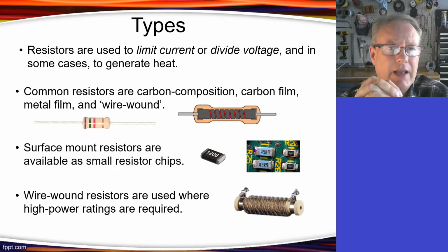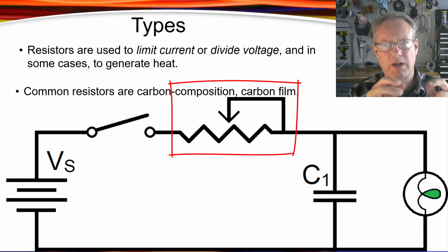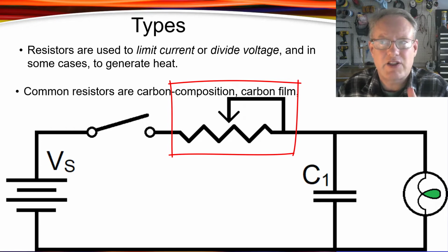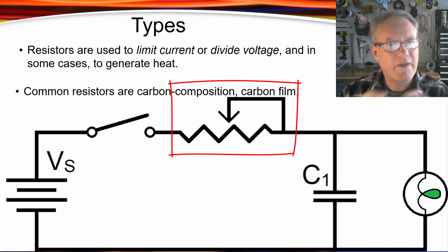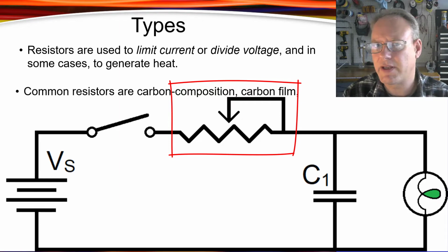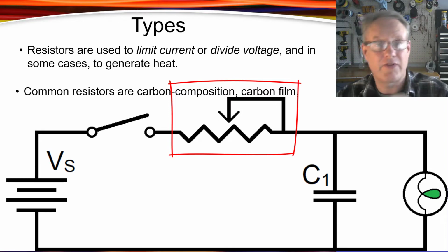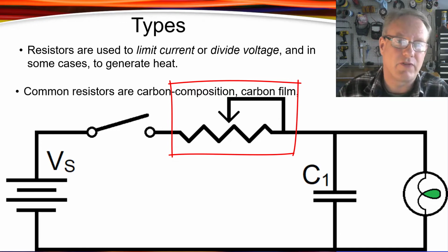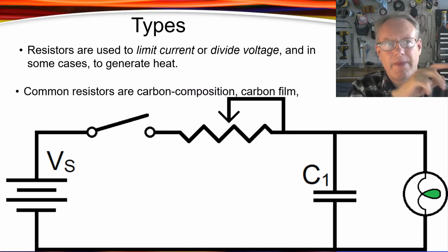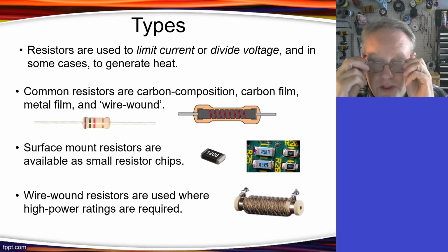And in a timer circuit, what's going on there is that we have a variable resistor that varies the flow rate, or the current, into a capacitor, and then it takes a certain amount of time to fill that capacitor. If I increase the resistance, I'm throttling the flow rate. Again, don't tell anyone I said that. So I'm slowing the flow rate down with this resistor, and I can increase that so it takes a long time to fill that capacitor. And once that capacitor gets to a certain voltage, it triggers the circuit. Or I can lower that resistance quite a bit, and then the current into the capacitor is a lot higher, and it fills more quickly. So you'll see those in circuits as well.